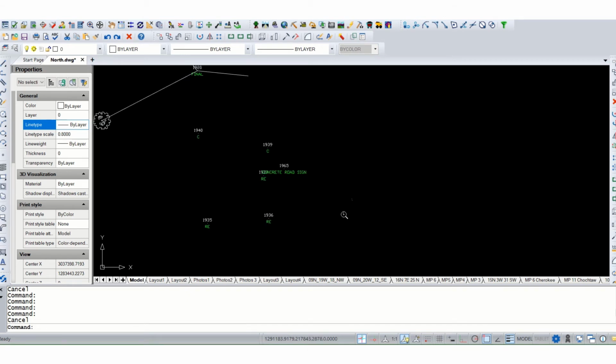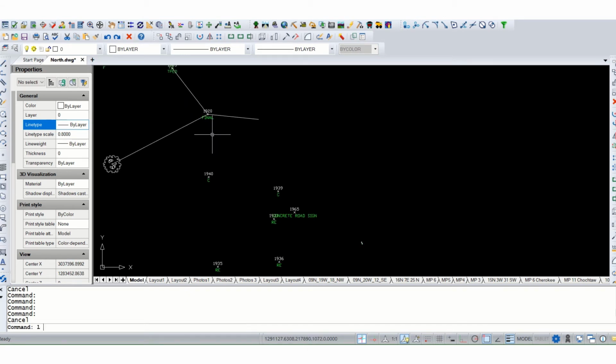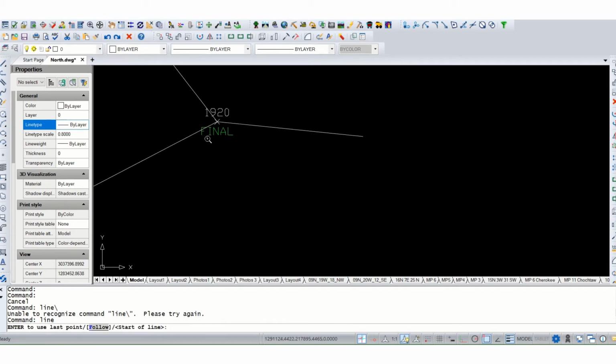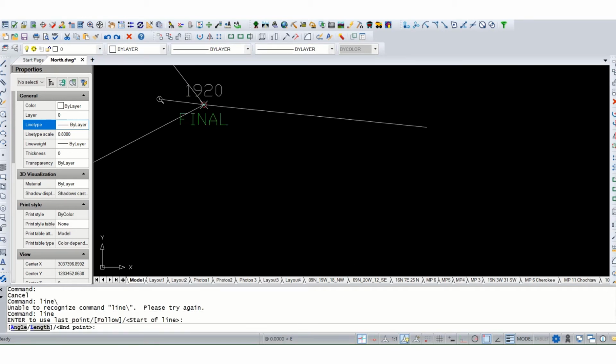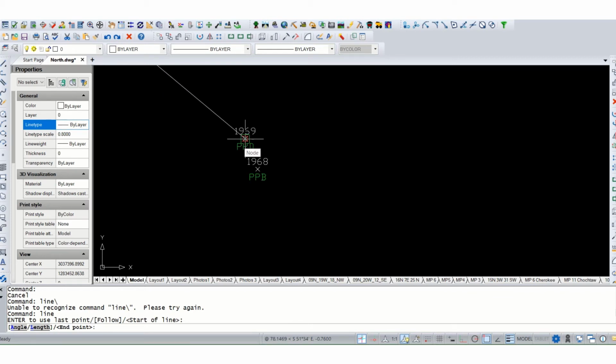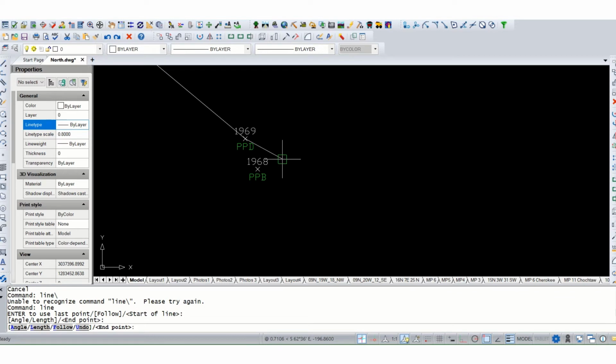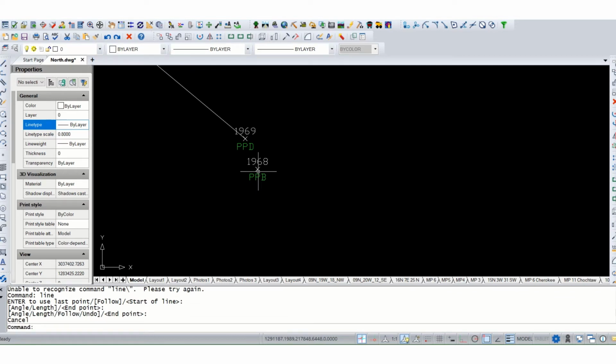I think I've got another power pole down here. Yep. Let's do that again, same procedure. Draw a line to the distance shot. This time I stood on the back side of the pole because I had more sky to the south and was able to get a better fix.